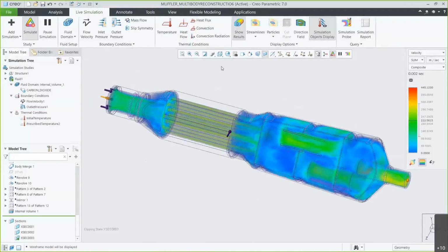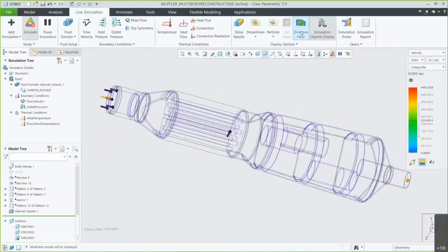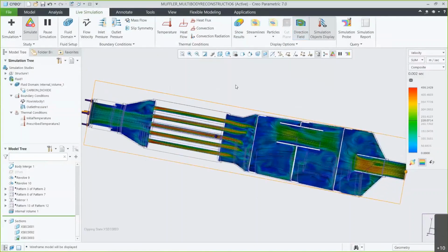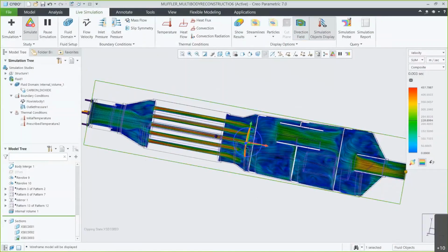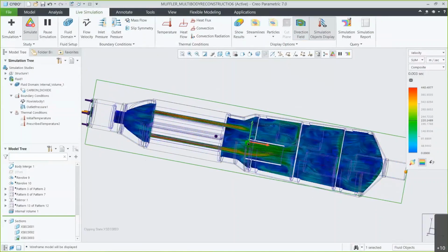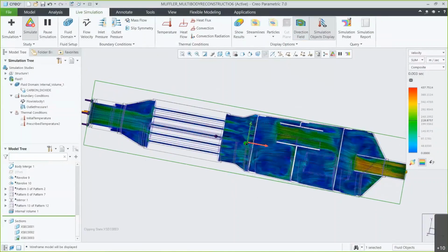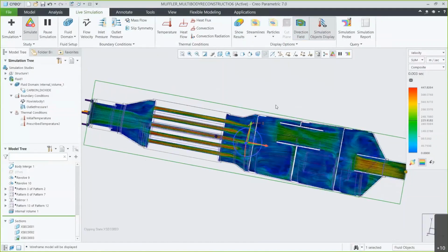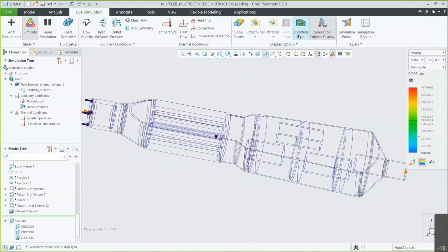We also can look at a direction field. So this direction field acts as a cut plane that I can use to see the direction everything is going. I can move that cut plane around to different parts of the model. So first here I can pull up the dragger tool and change that around and kind of see the direction I want to move it around from, see how that is moving based on how I define my model. Helps me interrogate certain areas, even if I want to type in specific values for that section, go through and see at very particular points in the model.